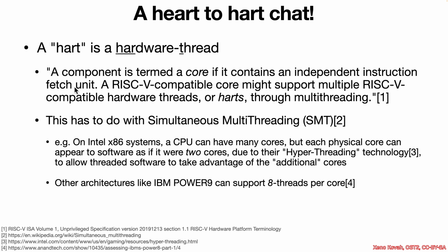So what is a hart? A hart is a hardware thread in RISC-V terminology. The way they define it, a component is termed a core if it contains an independent instruction fetch unit, and a RISC-V compatible core might support multiple RISC-V compatible hardware threads, or harts, through multi-threading.